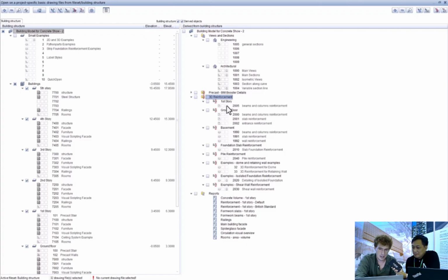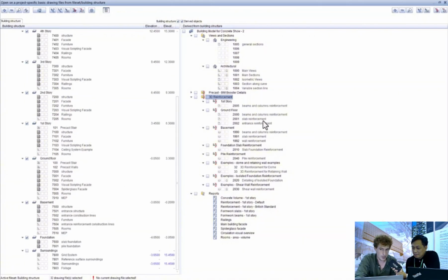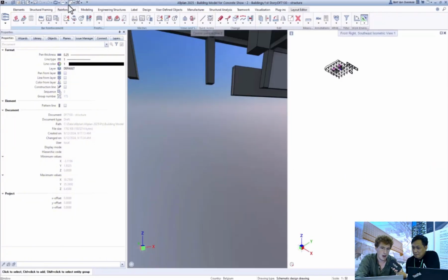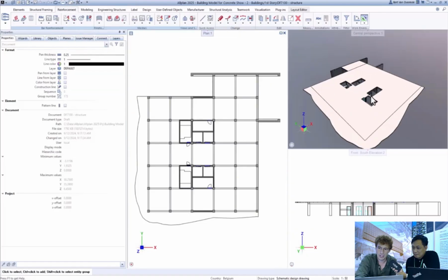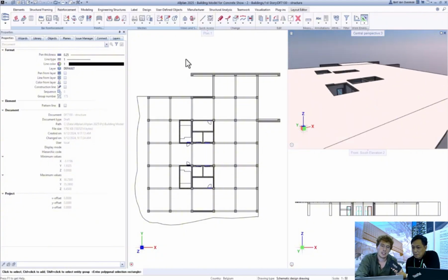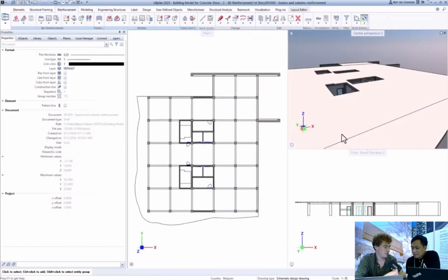So if you want your reinforcement also exported to an IFC file, you would put it on the left side. Okay, let's maybe go ahead and say, what do I want to reinforce today? We'll start with the first story. So let's take the structure of the first story. This is our structure. If we open our structure, we would see that it contains a few walls, columns, and a slab. And let's open a second drawing file, the first story reinforcement, which is an empty one, and leave the structure active, but this one is the one we'll be driving on. So nothing changes visually, but we are now in a different drawing file.